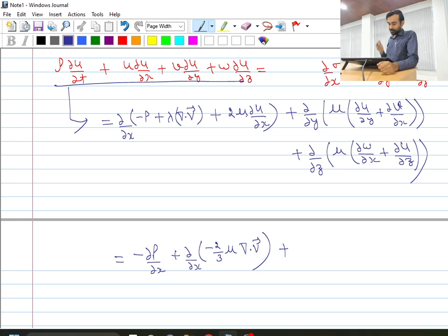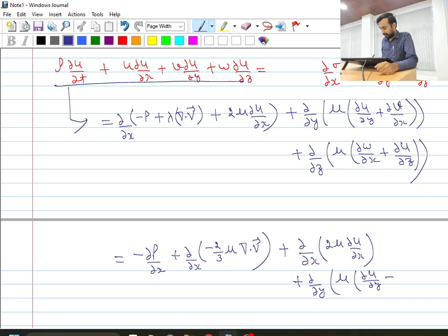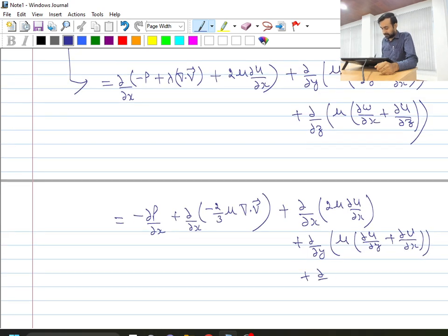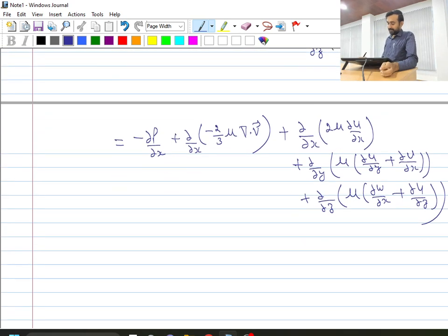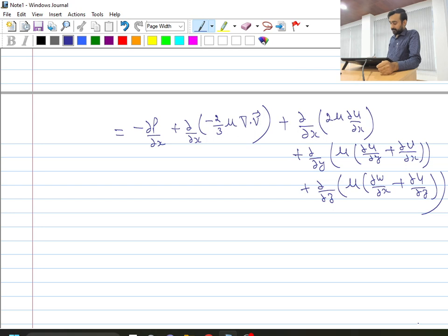now we will try to do something over here. Let me first write it: del by del x of 2 mu times del u by del x, plus del by del y of mu times del u by del y plus del v by del x, and then plus del by del z of mu times del w by del x plus del u by del z. One important thing we will now be substituting over here,